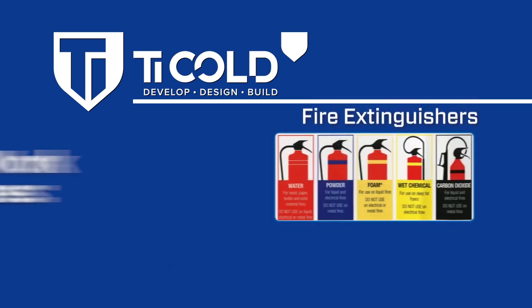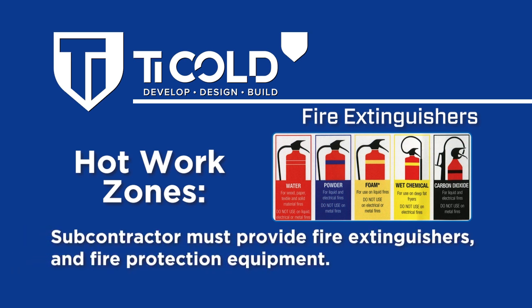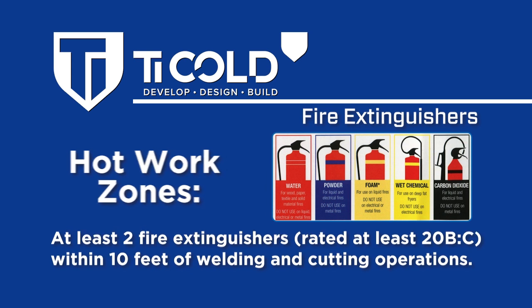Fire extinguishers. Hot work zones. Subcontractor must provide fire extinguishers and fire protection equipment. At least 2 fire extinguishers rated at least 20 BC within 10 feet of welding and cutting operations.